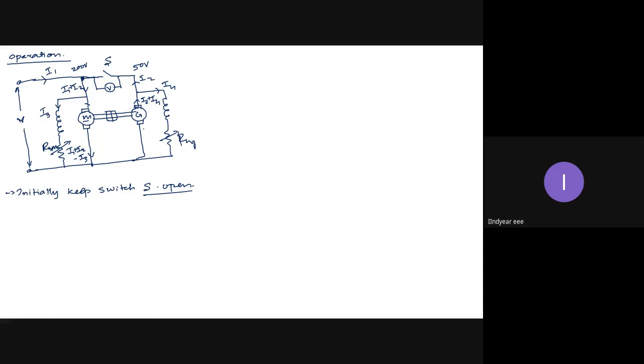What is the potential difference? It is 150 volts. So 150 volts is existing across this loop against the minimum resistance of the armatures. The armature resistance is hardly 1 ohm, so 1 ohm plus 1 ohm is 2 ohms. In this loop, there is 150 volts against 2 ohms. What will be the current? 75 amperes. So these machines will be carrying 75 amperes of large current, which is not a load current. That is a short circuit current.